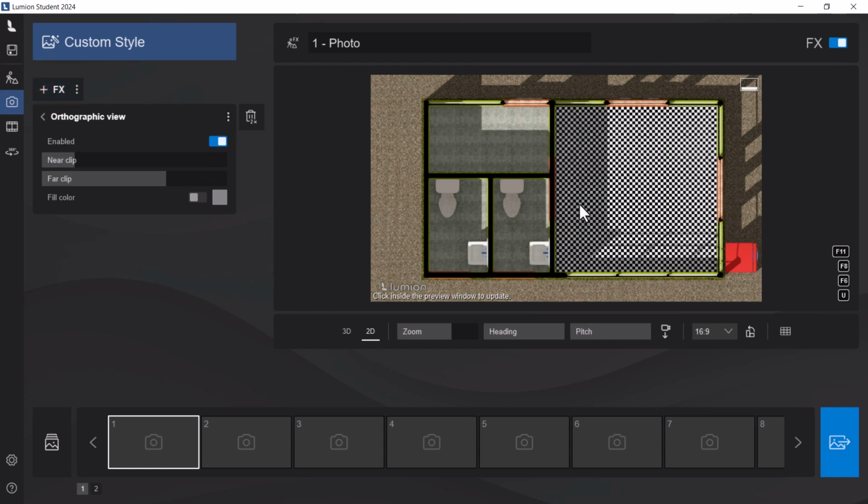This is, of course, inconvenient because your perspective views will also have section boxes available unless you launch Lumion from those views. So you might have to do separate sets. Export your plans, then change the section box in Revit, export your sections, and then remove the section box in Revit and do all your perspectives in Lumion.